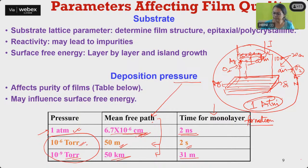So instead of 1 atmosphere, we now have 10 to the minus 6 torr. Now this Ag atom will travel 50 meters before it encounters anything else in its path. So it will evaporate here and directly come and sit here. This atom, if it evaporates, will come and sit here. And then whatever surface kinetics there is, it will form different clusters and so on. That is a surface phenomenon of the substrate.